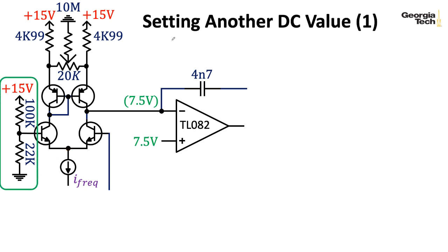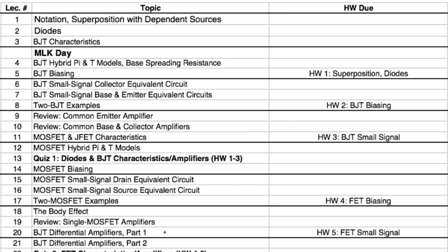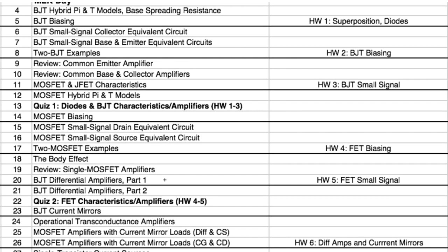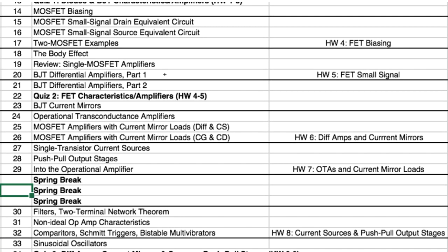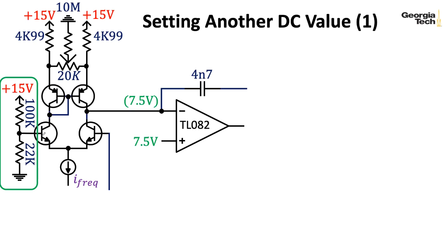Okay, so let's look at the 15 volts being split down the 100K resistor and the 22K resistor on the left. I'm going to assume that this transistor has a pretty big beta, and beta is sort of an imaginary parameter, but it's kind of useful. Anyway, I'm going to assume that the current flowing through the base is negligible, and that's an assumption I'll always make in this class. In a class like ECE4450 Analog Electronics, I generally would not make that assumption off the bat. Anyway, because we're assuming that the current flowing through the base is negligible, I can again just use a basic voltage divider.